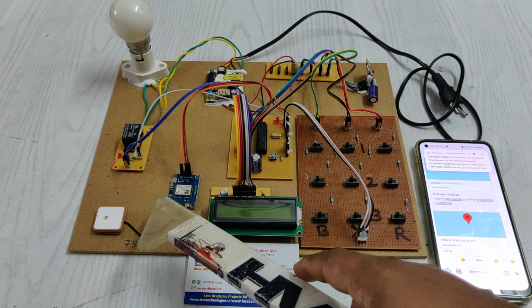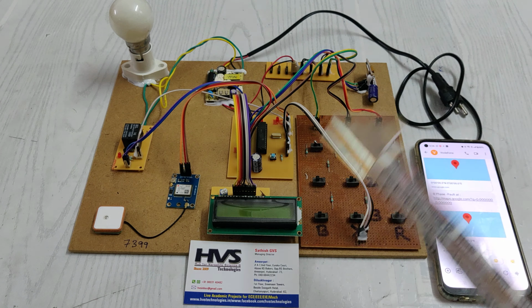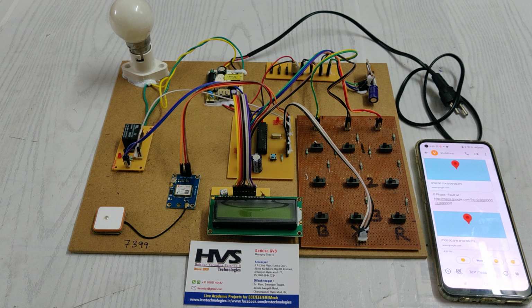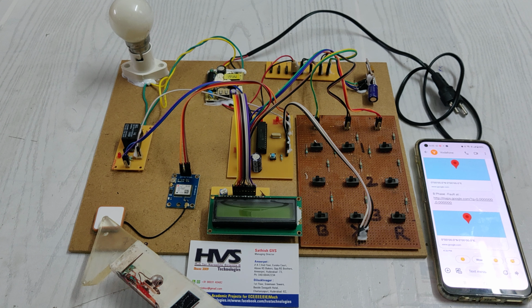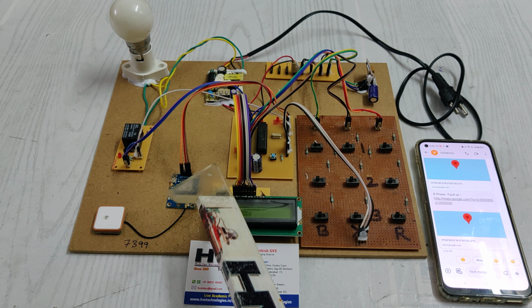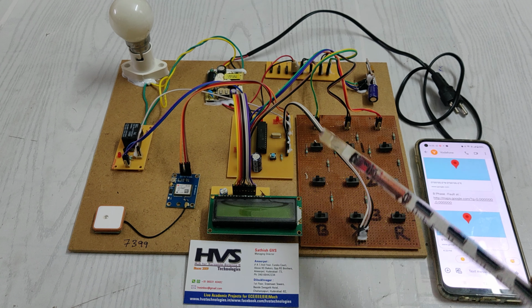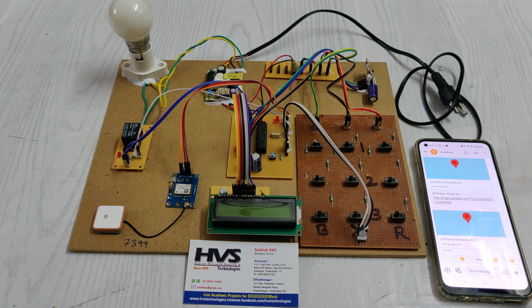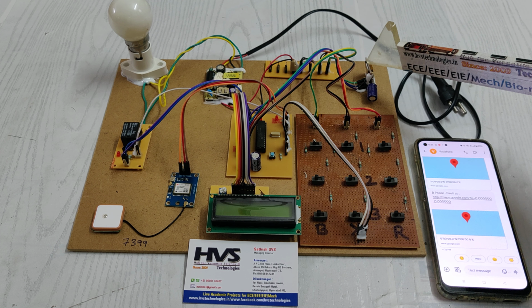At the same time we get the distance, meaning the live location where the fault occurred, and that will be plotted on this message link. To get the location we are using the GPS module, which is interfaced to the microcontroller, with the GPS processor and this antenna. The SMS alerts will be sent to the registered phone number with the help of this GSM module. We are using the SIM800L GSM module here.